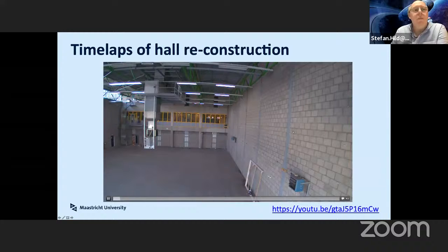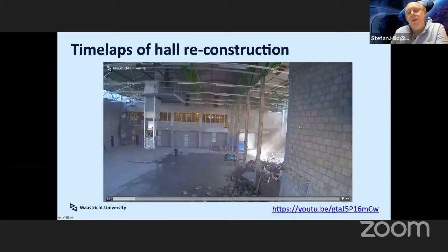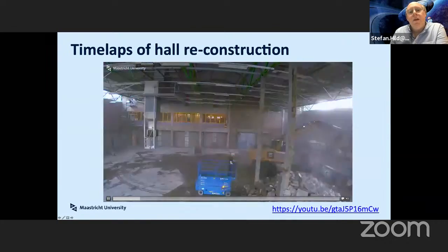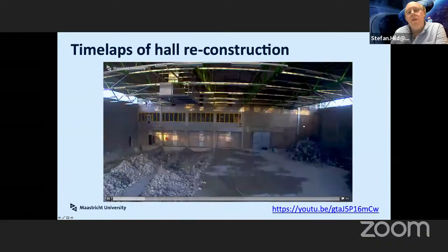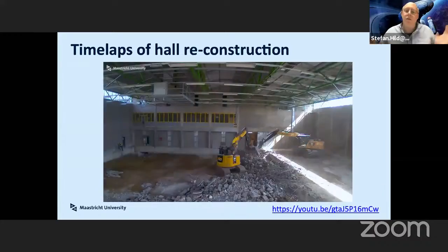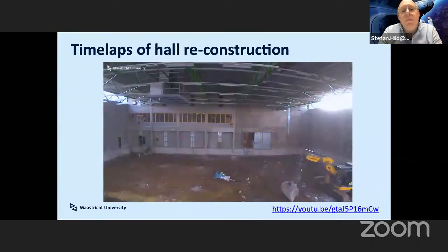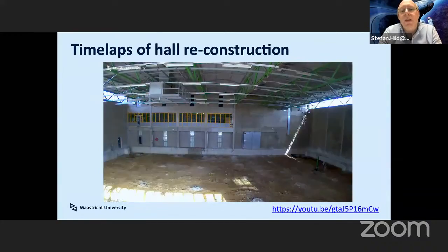So it was originally something which was consisting of 2 different halls. We pull the walls down here, take the old concrete floor out because it was not giving us enough stability and inertial mass. As I said, it was connected to the walls and things like that. And we put in a big slab, which is 0.5 meter thick.